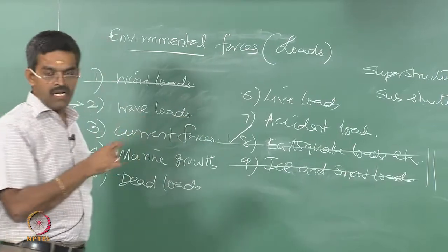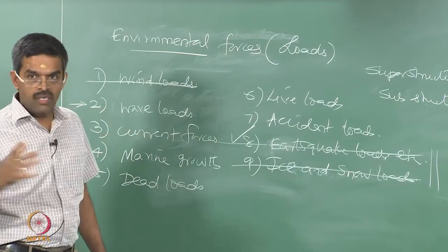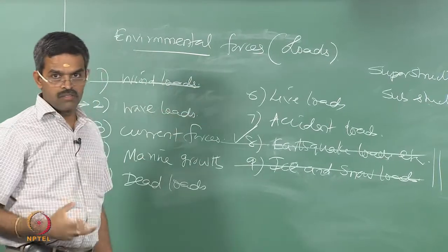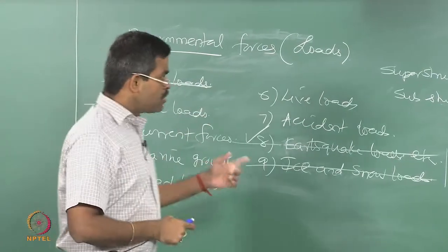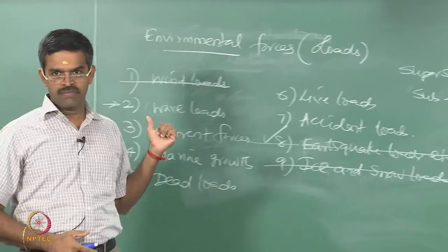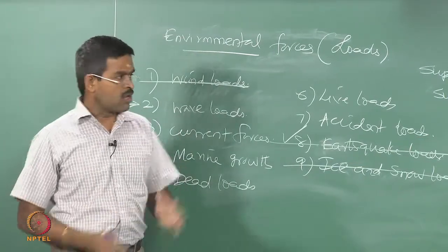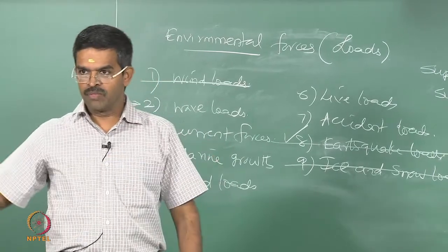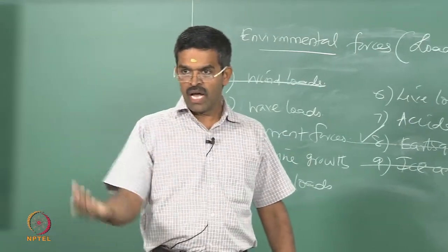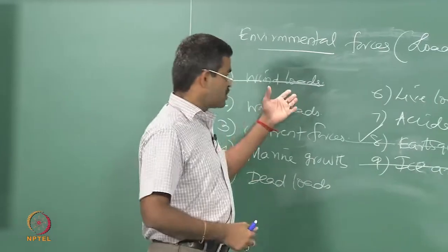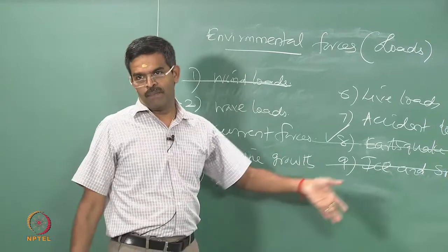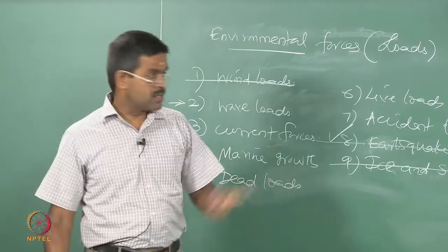So, please understand, our focus here is not calculating the forces on the structure. Then what is the focus? The focus is what is the response of the structure for these forces. Very important, we are talking about dynamic analysis, whereas in every analysis problem you will always compute the forces and the displacements. Here the forces are given to you, you should be able to estimate the forces from the standard spectrum. What you do not know is the response.